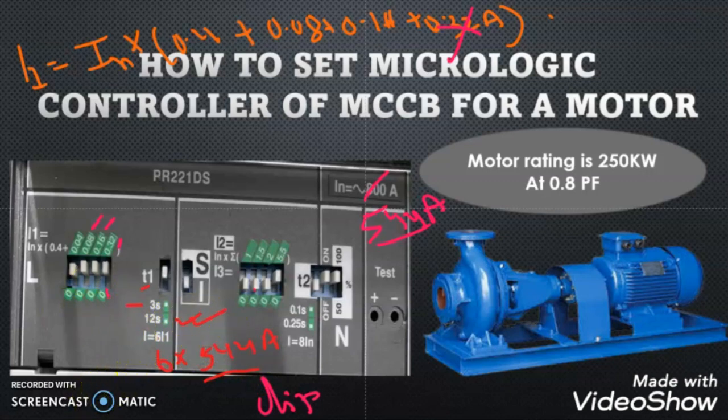As we know, the starting current which comes in the motor at the time of starting is temporary. It will last a maximum of 3 to 4 seconds, or for a bigger motor it can go till 6 seconds. So what the breaker will do is, when we start the motor connected with the star delta technique, the motor will take 3 times its full load current.